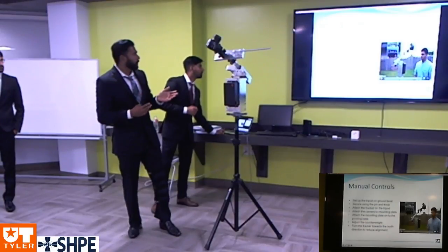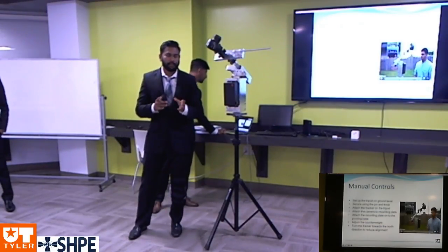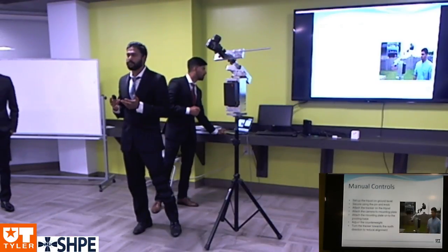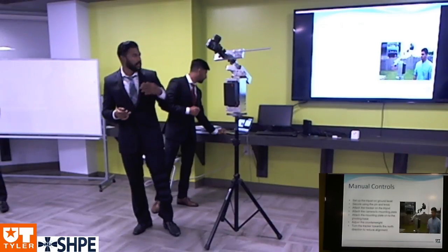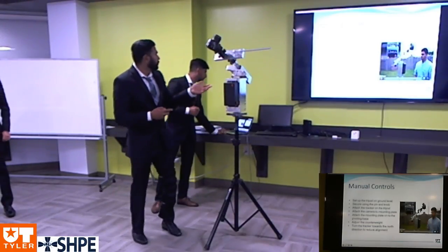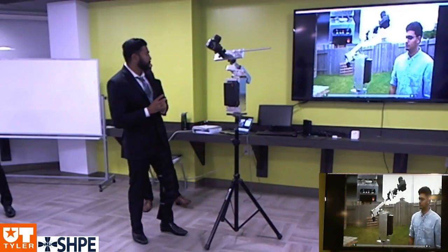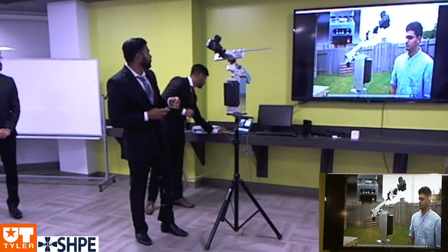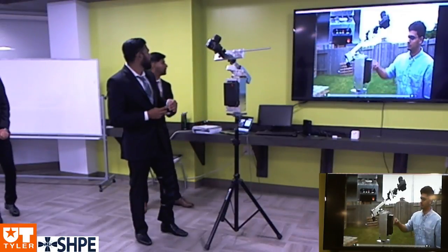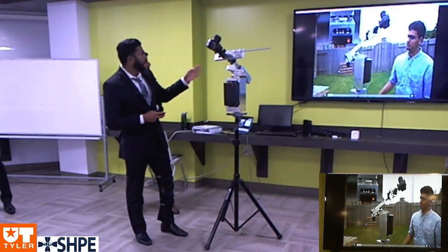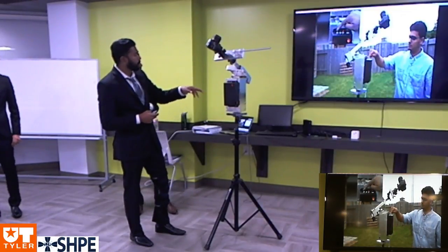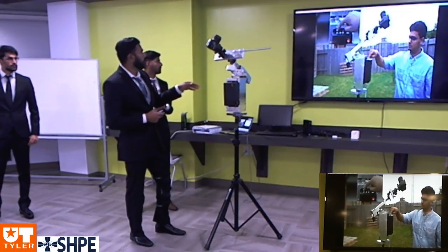I know it's programming, but the GPS works based on the location, right? If something happens, we should still be able to do the tracking and the alignment. That's why we added manual controls. Manual controls are pretty easy. You just press the red switch, which is an interrupt button, and it will start manual mode. First is the elevation alignment, and you can use the left and right switches to move it up and down.